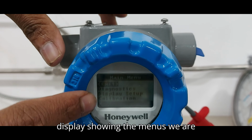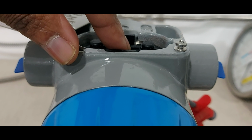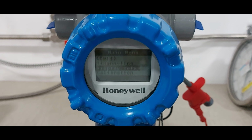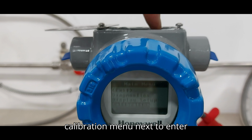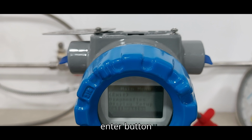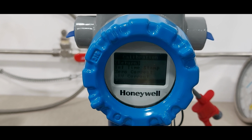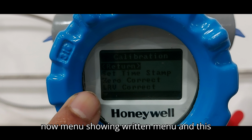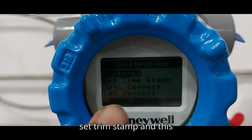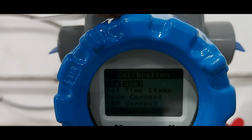The display shows the menus. We select the down arrow, calibration menu. Next the enter button. Now the menu shows return menu, set time stamp, zero correction and LRV correction.